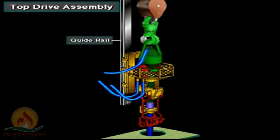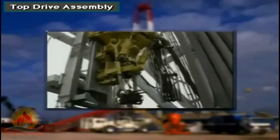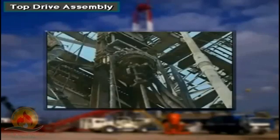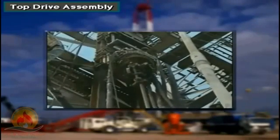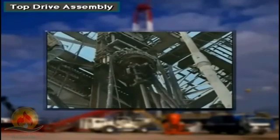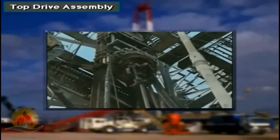Guide tracks or rails in the mast keep the top drive unit from rotating as the motor and the drive shaft assembly turn the drill string. The top drive dolly assembly moves up or down on the guide rails. Service loops, which are bundled cables and hoses, transfer the required electric, pneumatic, and hydraulic power between the mast standpipes and the junction boxes located on the top drive.